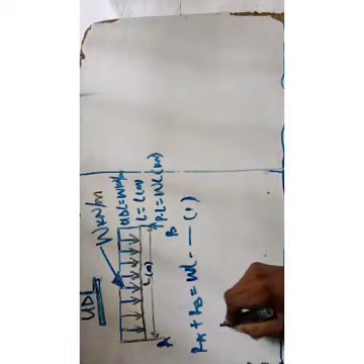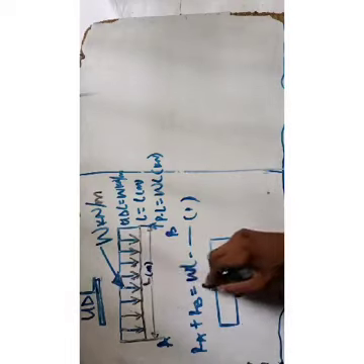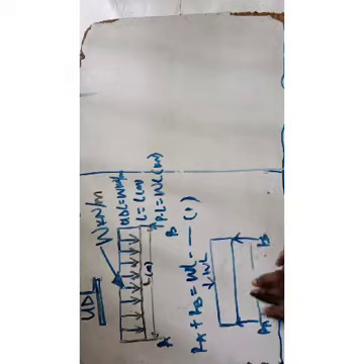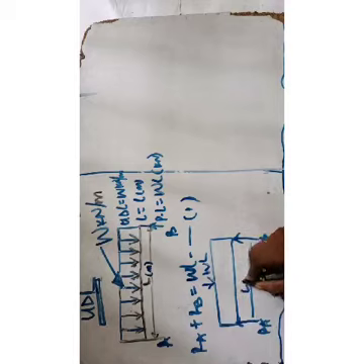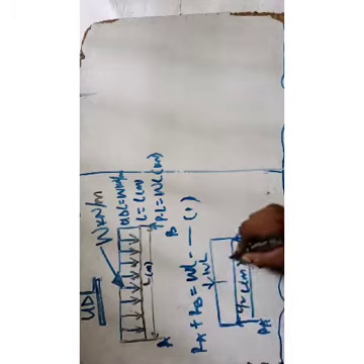Now when you convert to point load, the diagram changes, okay, and it will act at the center. So you're going to have the diagram like this. This will act at the center, that is WL. And you have your normal reaction RA. You have your second reaction RB. You have the total length it's covering, which is your L in meter. So remember, when it acts at the center, you have L over 2.